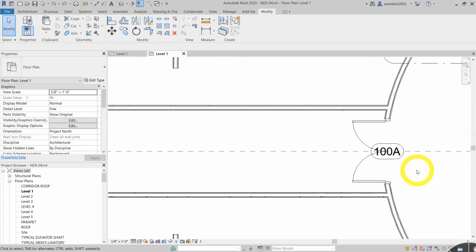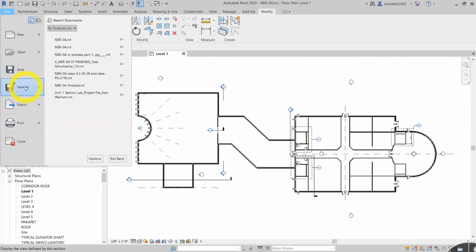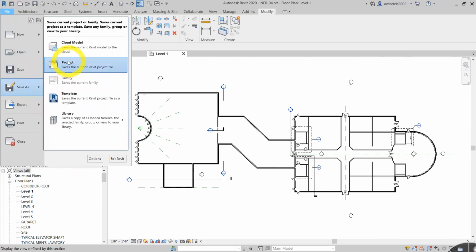Sometimes you can over constrain, but we're going to do the split element command on 201. It's basically like the break command in AutoCAD, splitting walls. You edit them in sketch mode, splitting in sketch mode. You can split elements and not in sketch mode. So we're going to go to the west wing wall section view. So let's zoom all again. We'll hit save for now. I'm going to hit save as. I'm saving this as an instructional video.